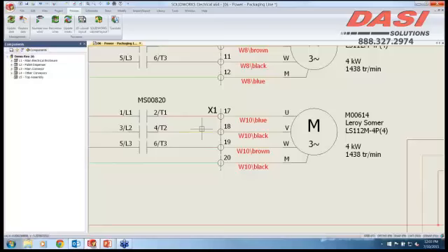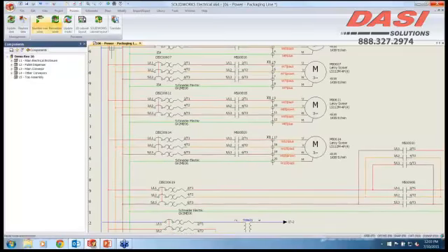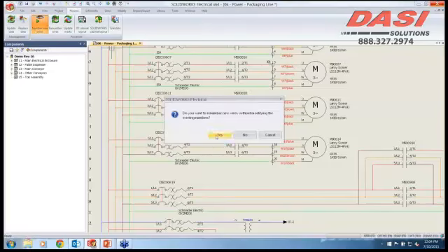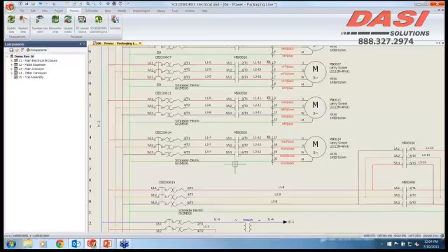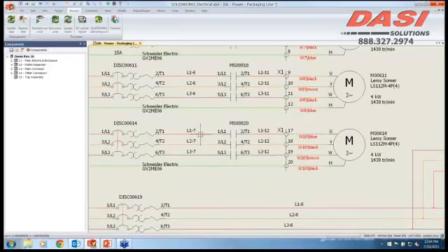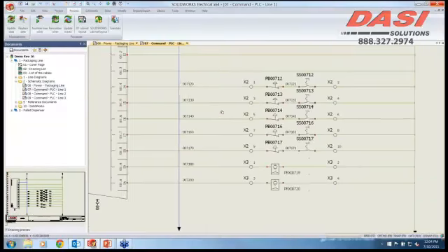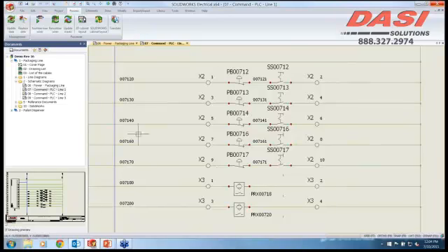So I'm going to jump right into our software. Here I'm going to show you that we have a process for numbering new wires, and it is a one-button click. You number the new wires, and it will ask if you want to do the existing wires too, or leave anything that was existing prior if you did anything manually. As you can see right here, we have all of the three-phase taken care of. If I go to my document tree and look at some of the PLC wiring, these wires have automatically updated.